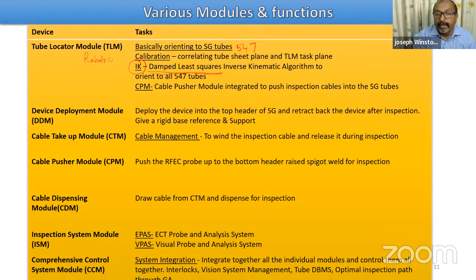All these have to be taken together. Otherwise, what would happen is suddenly the motors will see enormous current due to sudden accelerations of the motor system, and the currents drawn will blow up the fuse and completely halt the system for a while unless you reset everything.